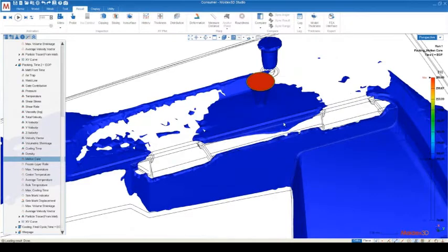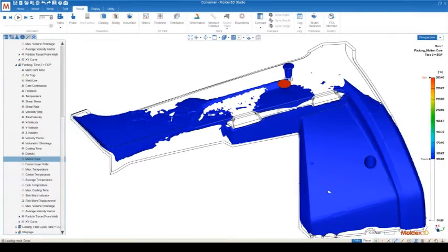If I continue to apply pressure, that material is only going to be packed into this region. I'm going to pack out this volume insanely well, but not the rest of my part. So I'm going to get a really low shrinkage around my gate, but the rest of my part is still going to be at a relatively high shrinkage.